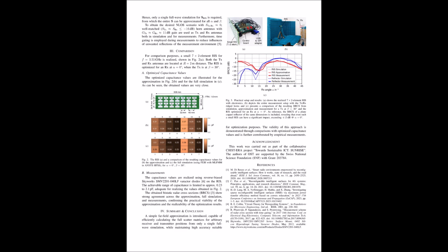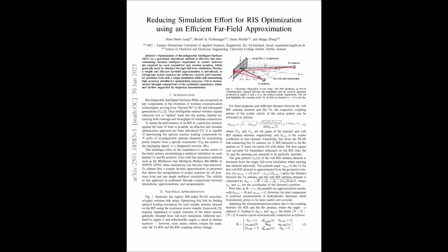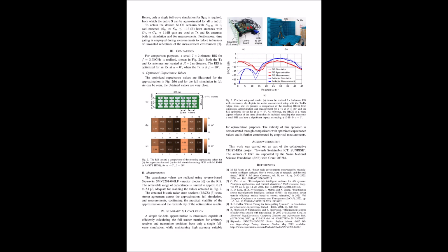Amazing. But how do they actually implement this in their physical RIS? What did that setup look like? They essentially built a small circuit board. A circuit board, okay. And on this board, each RIS element was connected to its own varactor diode. So a one-to-one mapping. Exactly. And then they used a microcontroller. A microcontroller, like a tiny computer brain. Yes.